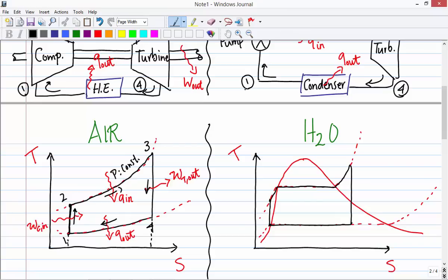In an ideal Rankine cycle, point one, which is the outlet of the condenser, would be a saturated liquid, right? Because what are we doing? We are condensing a vapor, and as soon as it gets to the liquid phase, that's what we want. We want water, we want liquid. So at that point the quality, X, would be zero because it's all liquid. There's no vapor anymore. So in an ideal case, point one would be right there on this curve, on the left side of the curve, which represents the saturated liquid.